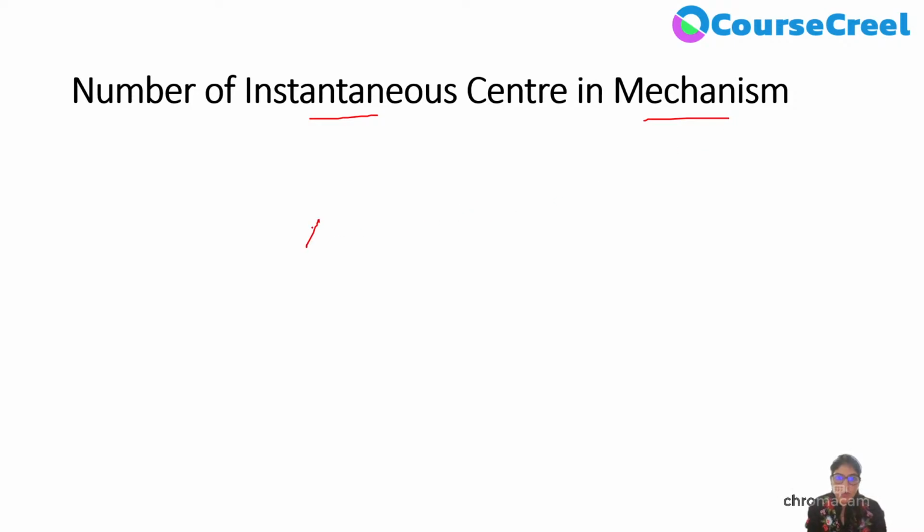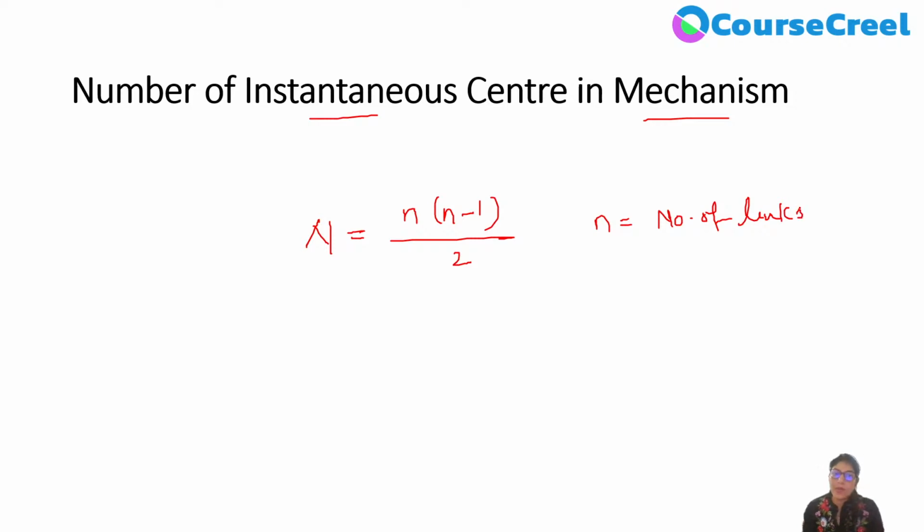Okay, for this there is a formula, that is called N equals to n into n minus 1 by 2, where n, small n, is number of links. n is number of links. Okay, so instantaneous center is calculated on the basis of number of links. Number of instantaneous center, we denote by N. But how do we define it? Maximum number of possible combination of the kinematic chain.